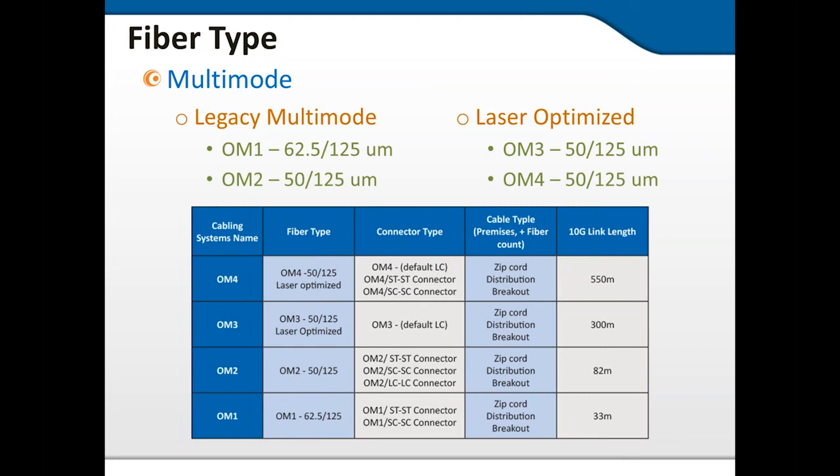Then the standards were tightened up. The ability to manufacture a smaller core came into play, and we dropped down to a 50 micron core, which is, by the way, the international standard. That's the standard we have on most of the ITU international standards and what I deal with when I talk to people in Africa and the Middle East. It gave us the ability to have the length stretched out to about 250 feet. Really what it comes down to. Getting close to 300 feet.